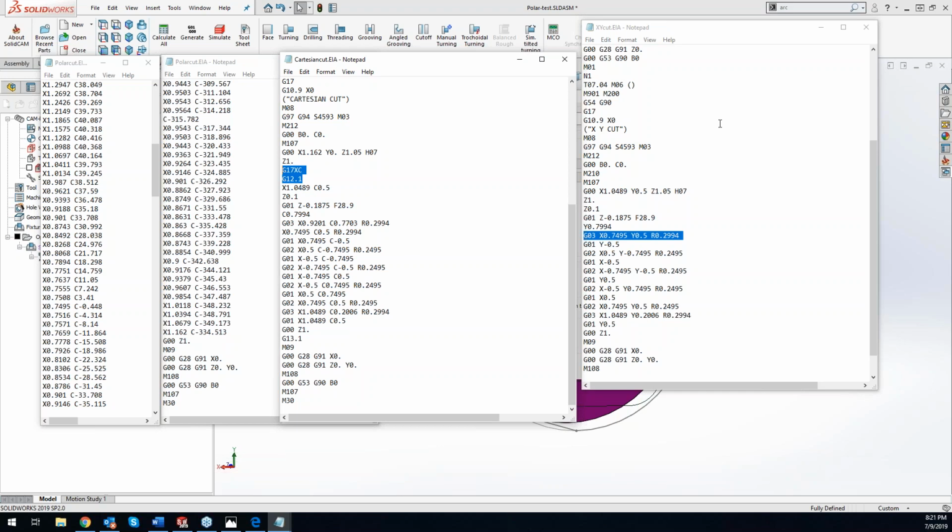Like Greg was saying, it's very machine dependent on what your machine can support. So this one is on a Mazak, so we can support all the different ones, but it's per machine basis. So if any of those come up, or if you want to run that code and you're getting an alarm out, definitely feel free to give us a call, but more than likely it's going to have to be switched over from Cartesian to polar to XY, which is just no fourth axis move at all, with the motion control turned on for you.